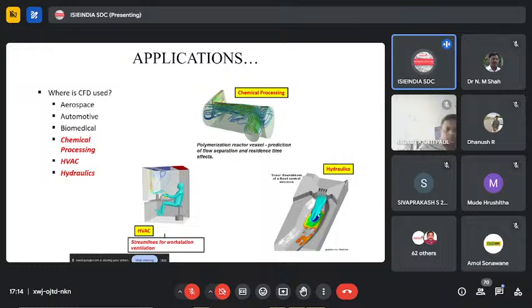Even in dams and hydraulics, the concept of CFD is used. It is employed to study scour downstream of flood control structures. By simulating water flow and sediment transport, we as engineers can predict erosion patterns and design measures to protect the structure from damage, and ensure the longevity and safety of the flood control system.